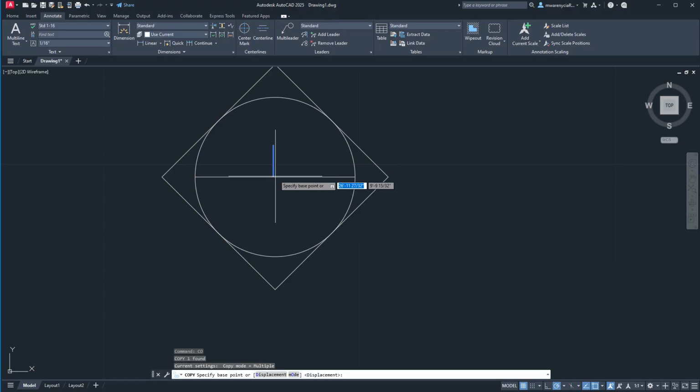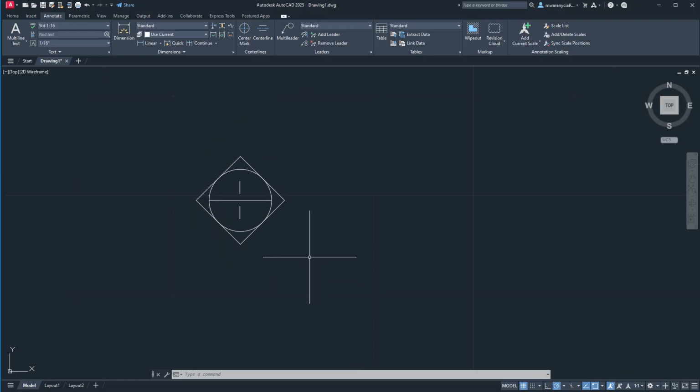Next, I'm going to copy this, and I'm going to move it up 1/32 of an inch. And then the original, the one that we put here, we're going to move this down 3/32 of an inch. So now, because they're that same height, they're the 16th of an inch, it leaves that 32nd of an inch gap between both of them off the center here. So we'll use this as our default right now, or a template.